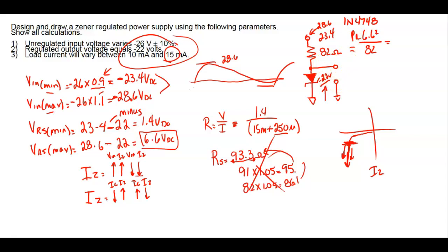So we're calculating the maximum power. We know that resistors are rated in three things. What are the three things resistors are rated in? This will be a good test question, by the way. I'm going to start putting that on every test I give. Ohms, watts, and tolerance. Well, we took care of the ohms. We took care of the tolerance, right? Now we're trying to calculate the wattage rating I have to buy for this resistor.